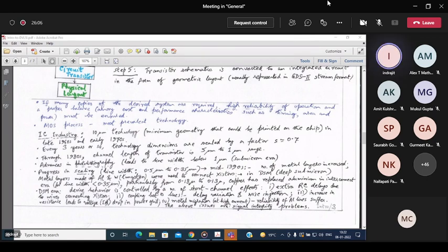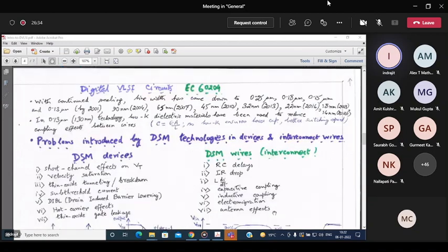So for metal migration, you have to tackle it by probably reducing the current, keeping a cap on the maximum current that can flow, and the reliability of aluminum lines suffered. That's why copper has mostly replaced aluminum. The above issues are signal integrity issues. That means whether the signal can be preserved at the proper values. It may have an undesired fall. Now with the continued scaling, line width has come down. This you can just study, it is very much historical.